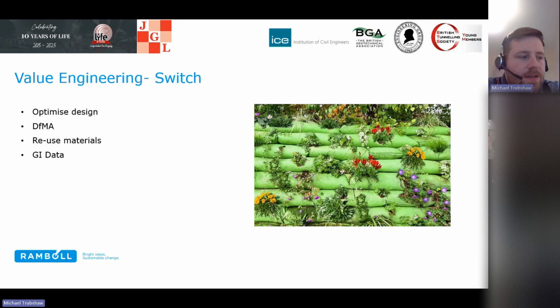And so if we think back to that carbon accounting and all the different modules like A1 to A5, if we use less materials, it reduces the A1 to A3. It also means we have to transport less materials, so there's less transport emissions. It means we have to spend less time constructing it on site, so there's less waste of materials, there's less emissions from all the plant and construction processes on site. It also means there's less materials involved in the refurbishment and the repair of it, and then there's also less emissions associated with the demolishing, deconstructing, transporting the waste, and then processing that waste on landfill, etc. So you can see how using less materials cascades throughout the life cycle of the asset.